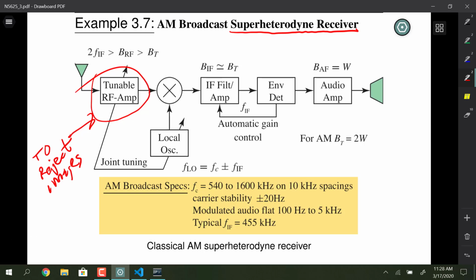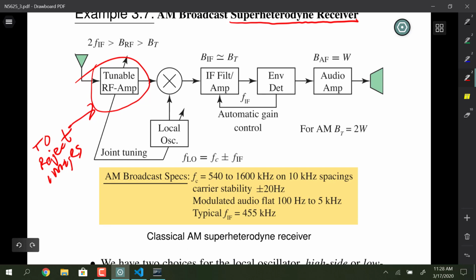And it's the frequency translation idea, where you have a local oscillator and you move the signal of interest to a common intermediate frequency so that it can be doing all the gain and the signal processing at one frequency, and you just make the local oscillator tunable. And that's used in everything radio, whether it's your cell phone, Wi-Fi, car radio, you name it. Everything does mixing like this and moves things to a common frequency for convenience.